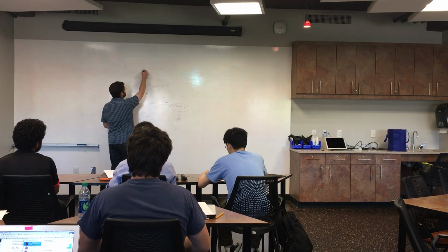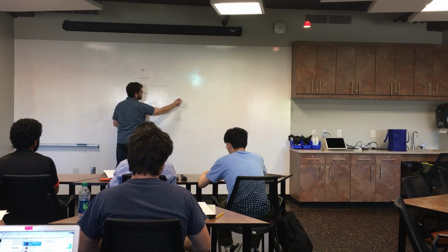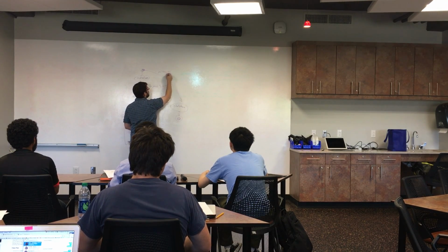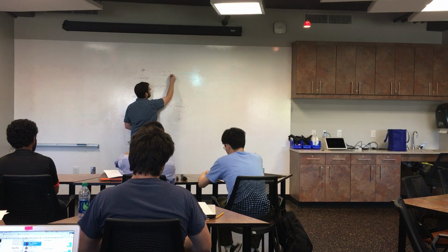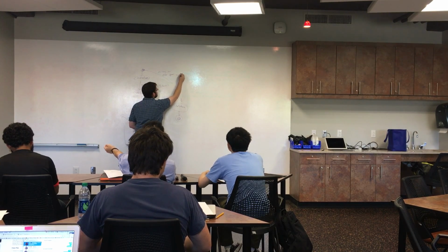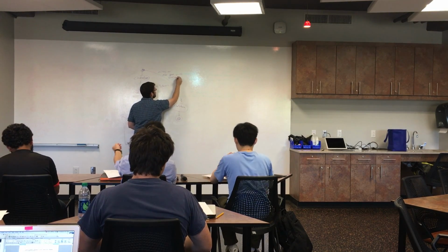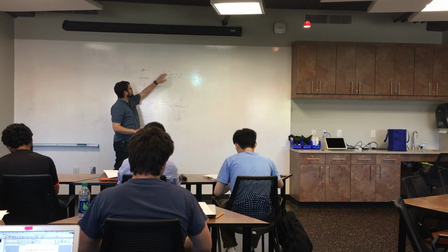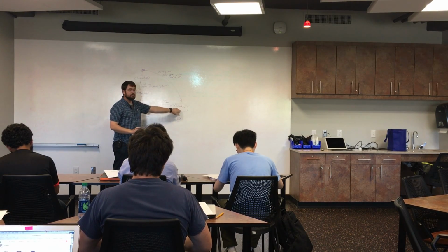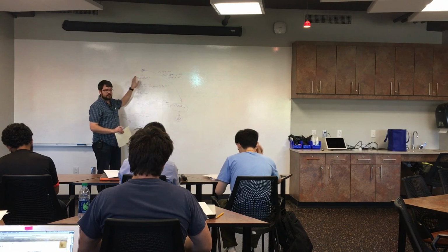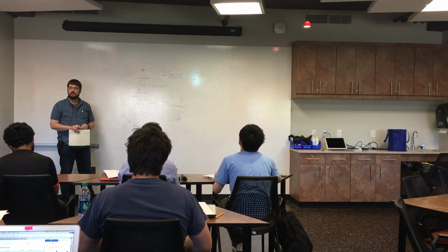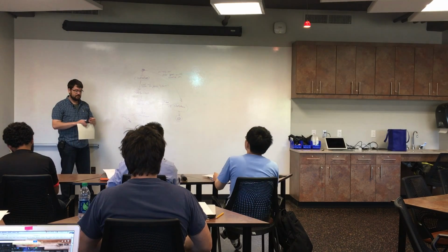And what's missing is, on a parallel branch here, we want error or door open with source on. So if the door is open and the X-ray source is on, or if there's any other kind of error, we want to immediately go to a shutdown state. And that's on a separate branch of this state tree because we want it to be running in parallel with everything else that's going on.